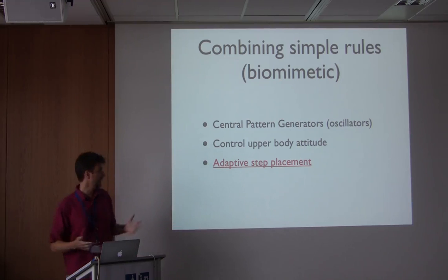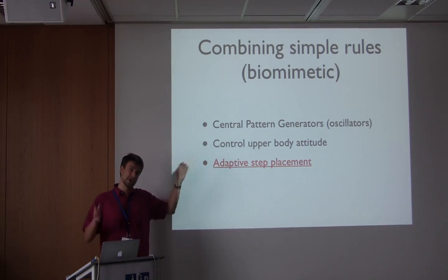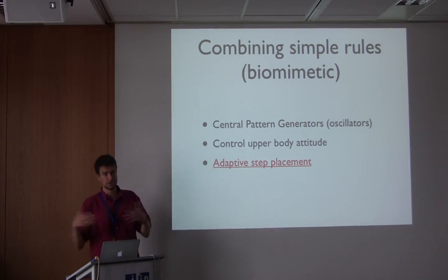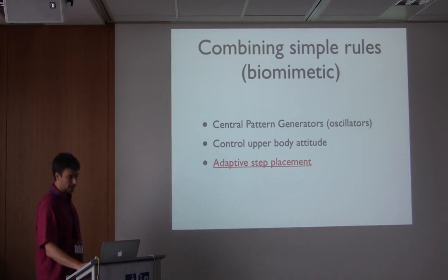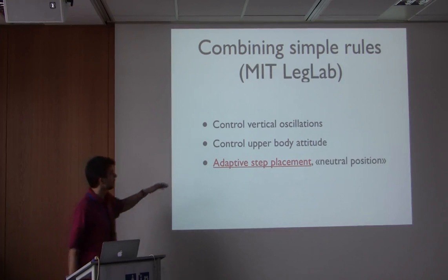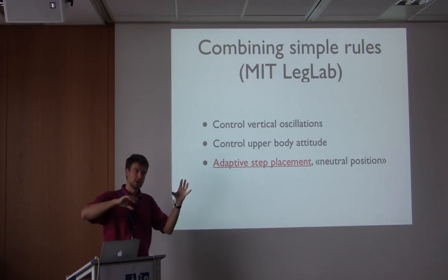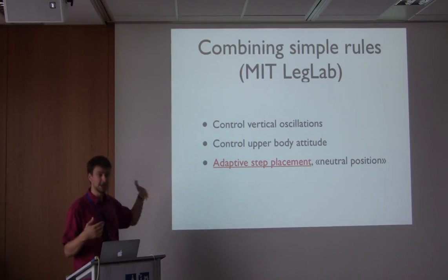What's important is then that you have some simple rule to stabilize, and especially either stabilize the motion of the center of mass with respect to the foot position, or choose the foot position with respect to the motion of the center of mass. So either you move your feet or you move the center of mass, but you use those two things, and that's it. And you can only use simple rules. However, of course, since people are using separate rules which are then combined, the end result is sometimes shaky, not optimal.